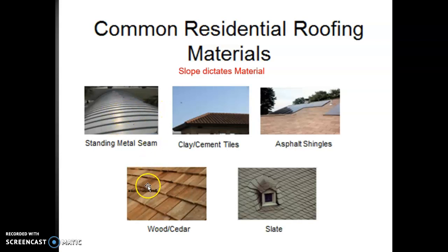Wood shakes and cedar shake shingles, again, you got to be careful because of the fire element with these. These tend to be restricted in most areas here in Fort Collins anyway, in a lot of areas, especially up in the mountains. I mean, what's going on right now with the wildfires is a great indication. And slate. The reason I put slate in there is the weight of slate. That's a big dead load on a roof.